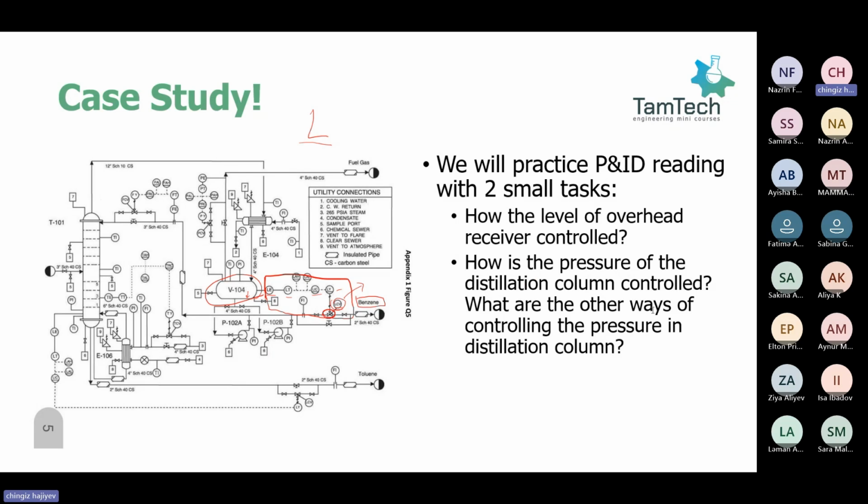Some, I guess, mentioned, for example, I can see the answers in this chat. Samra mentioned level controller: when the liquid reaches HHL or LLL, the valve is opened and closed respectively. And also, I guess, okay, this is the next question. Then level controller for, okay, good.